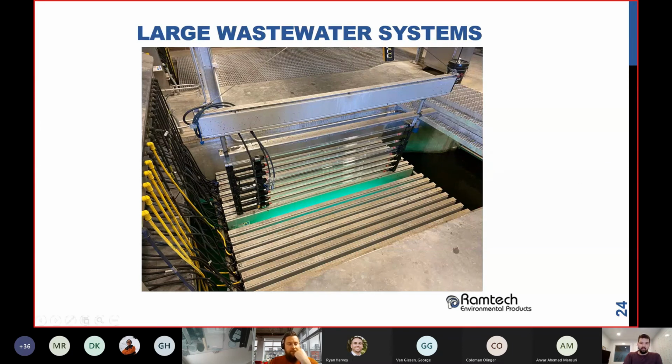You can see the UV light, the green there, that's coming out a little bit. If you're doing maintenance, you don't want to be staring at that a lot. That's why we have this here, called the light block. It keeps that UV light from reaching out, so always wear your eye protection and everything when you're doing maintenance.